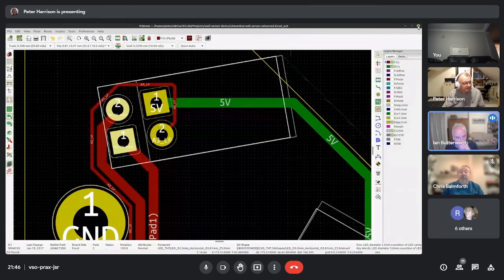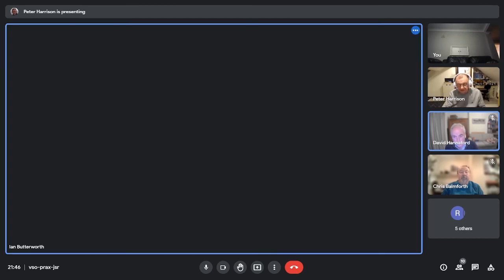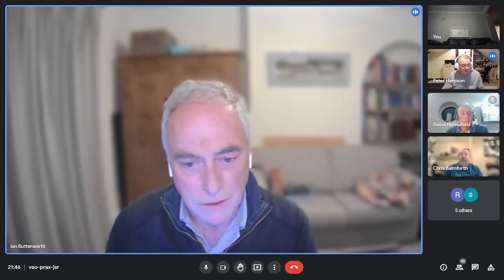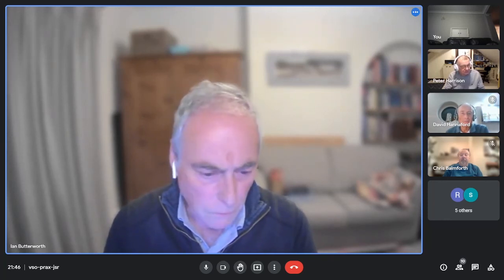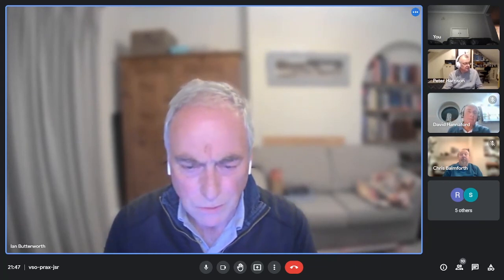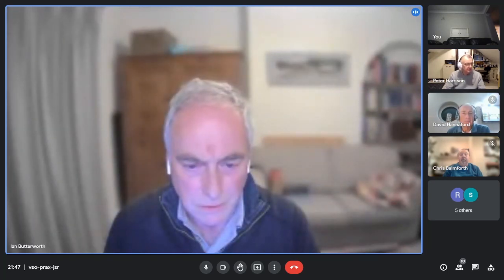Right. Okay. And in fact, if you want to stop presenting, I can show you what I came up with in the end for Mouse. But in the earlier versions of KiCad, you could change the amount by which your rotate component keystroke or mouse click did. And in the new version, it just seems to be locked at 90 degrees. So you can rotate it by 90 degrees, but not by less. And you actually do have to go into the individual footprint. I'll just show you the 3D model.